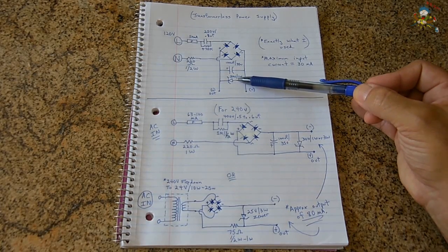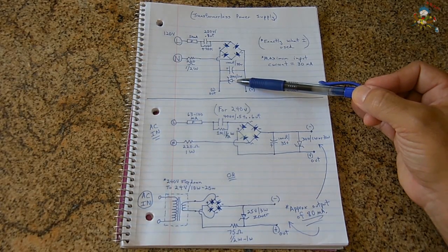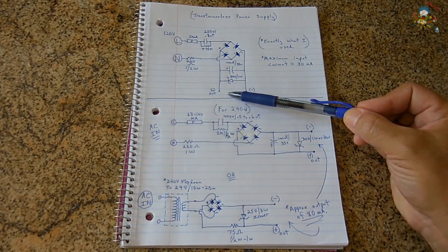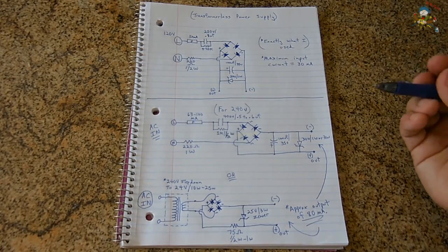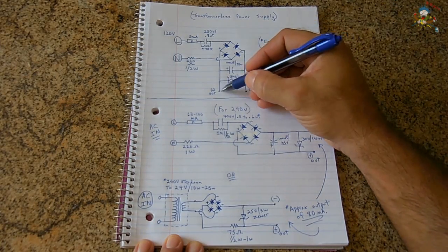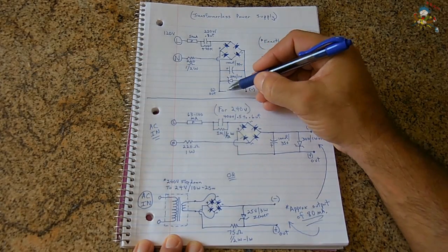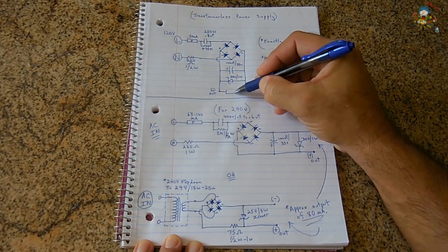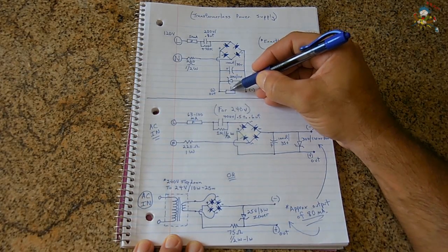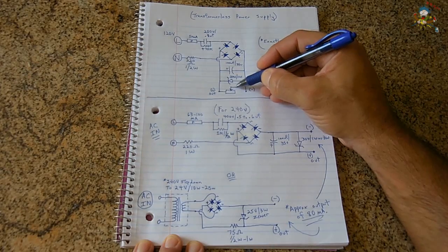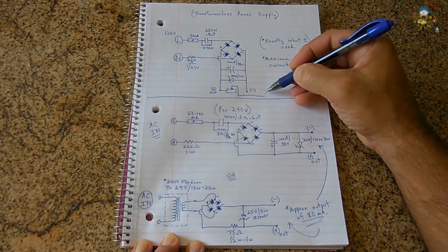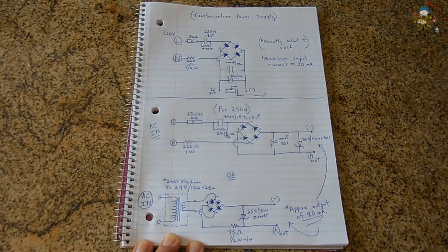So you're not even going to be anywhere near the 30. To adjust the brightness on the output right here, you're going to be using a potentiometer. Let me draw that in. So from the output, instead of this going to the LED strip, you're going to go in to one side, and then you go like this, and then like that. And then this right here would be your positive connecting to the LED strip.